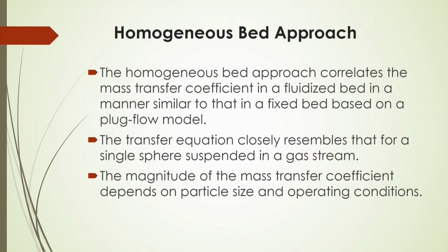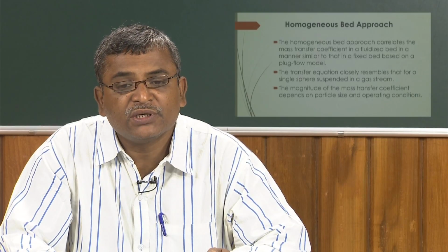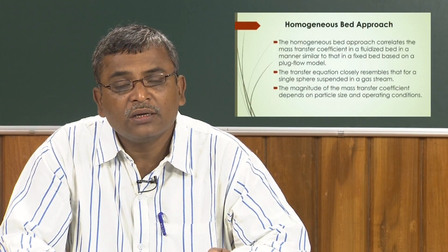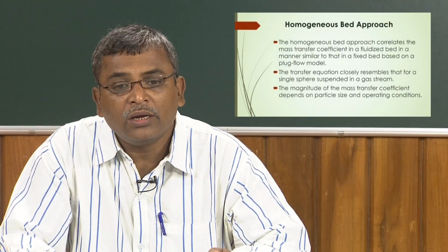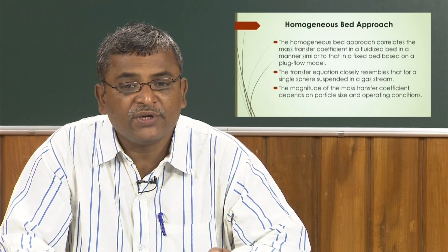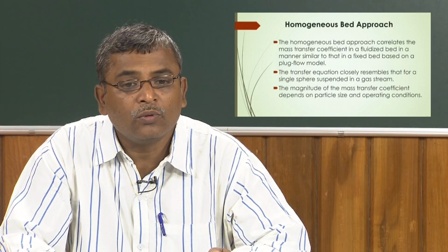We have told that there are generally two approaches to analyze the mass transfer in the fluidized bed. The homogeneous bed approach generally correlates the mass transfer coefficient in a fluidized bed in a manner exactly similar to a fixed bed, based on the plug flow model.